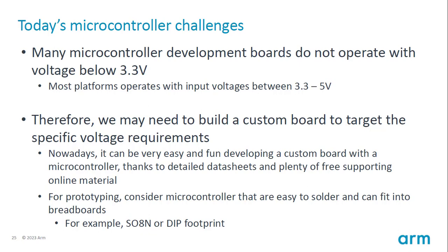Of course, something to keep in mind when you decide on a microcontroller, if you're just prototyping, remember that soldering could be a big challenge, so try to select a microcontroller where the pins on the chip are easy to solder.